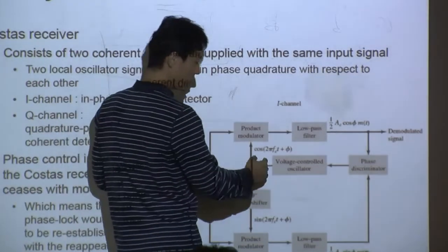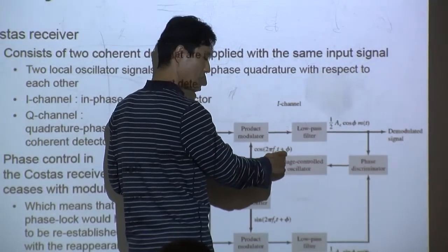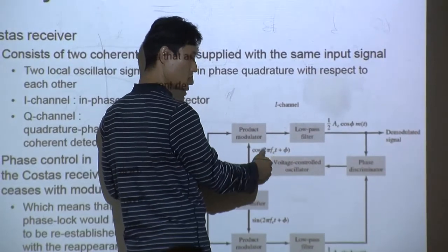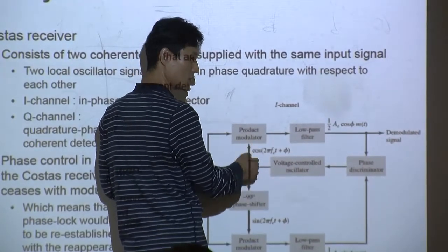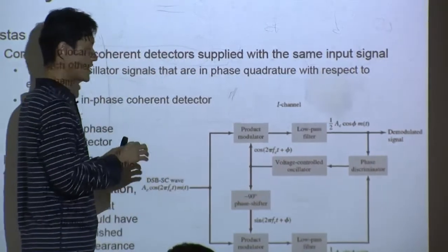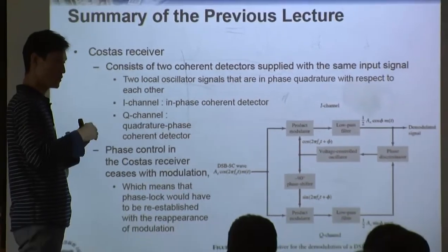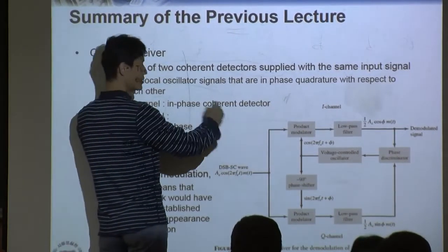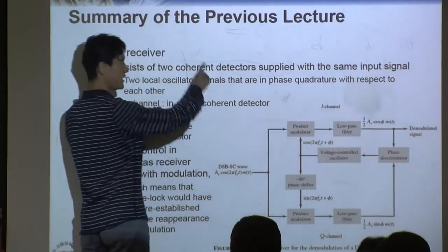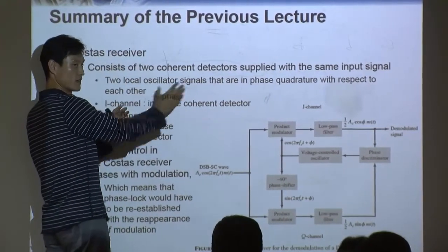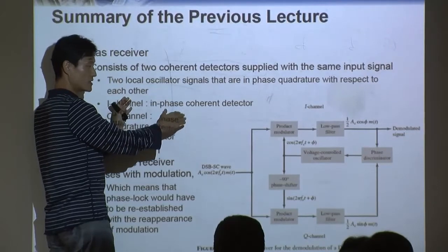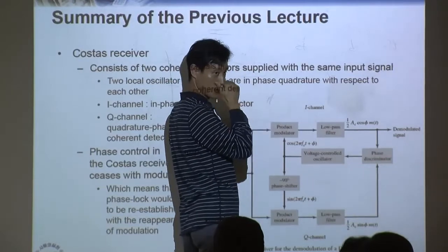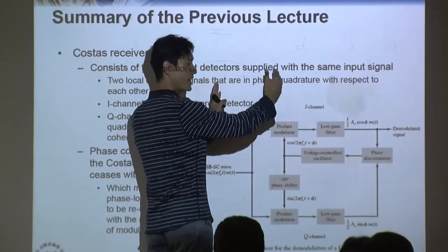So by doing that, when you have a phase mismatch, you're going to make the output frequency either a little bit faster or a little bit slower in order to catch up, so your phase becomes 0. You want to correct it little by little. Let's say your original signal goes like this and your phase is delayed, lagging, a little bit behind. In that case, you want to make it a little faster, right, in order to catch up.